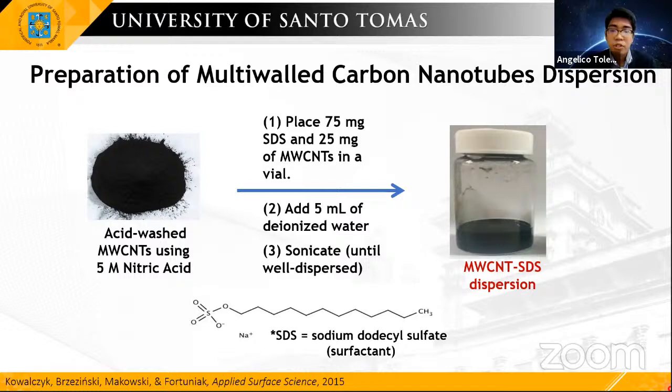So for the methodology, the preparation of the multi-wall carbon nanotubes dispersion is just a mixture of multi-wall carbon nanotubes, SDS, or sodium dodecyl sulfate, and water. And then the mixture was sonicated until well dispersed. And there you have it, a multi-wall carbon nanotube dispersion.